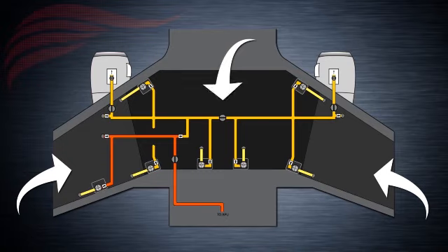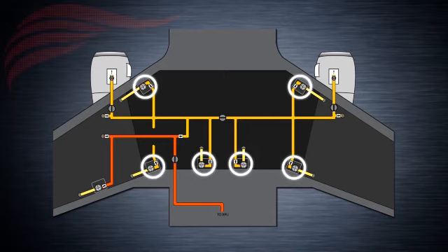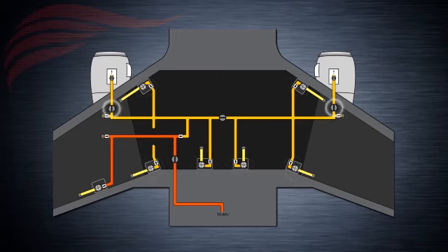Engines on the 737 ideally work with Jet A or Jet A1 fuel supplied from the wing tanks and center tank. This fuel is pressurized and is boosted into the engine system with booster fuel pumps. Immediately outboard of each engine strut, there are engine fuel spar valves. These fuel spar valves permit fuel flow from the engine feed system towards the engine fuel supply systems. There is one fuel spar valve on each wing.